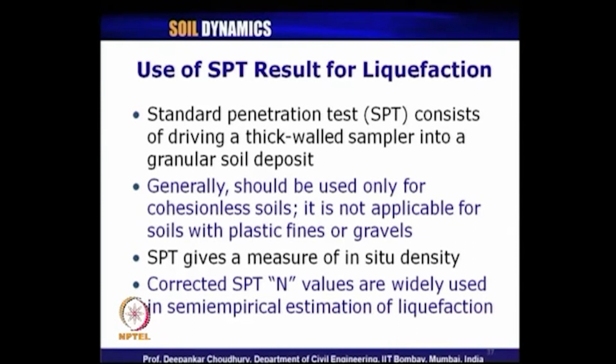SPT gives a measure of in situ density, and the corrected SPT N value is the number of blows required to penetrate a certain distance. As per our Indian condition, we measure the number of blows required for 15 centimeter, 15 centimeter, 15 centimeter, and for the last 2 15 centimeters we take how many blows are coming, that is nothing but the SPT N value. It is widely used in semi empirical estimation of liquefaction.